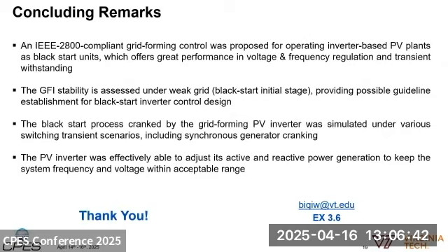We also have the simulation results of a complete black start process cranked by the GFI under various switching transient scenarios, including the cranking of a large-scale synchronous generator. Our GFI is able to effectively adjust its P and Q power to keep the frequency and the voltage of the system within an acceptable range.